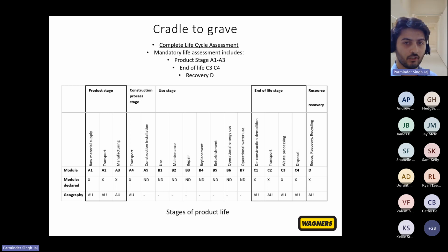These stages in the EPD world have their own acronyms. So it is denoted in alphabetical form. They are called modules, so A1, A2, A3 for raw material supply, as you can see on the screen. Same in construction process stages, they have different acronyms too. And this will be useful when we go through how we calculate and compare the emissions.